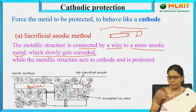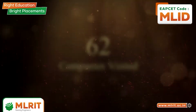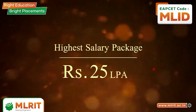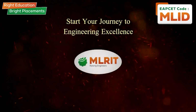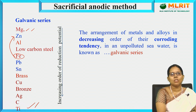Why have I chosen magnesium? Because when compared with an iron pipeline or stainless steel pipeline, magnesium is more anodic than iron. In this galvanic series we have magnesium, zinc, aluminum, low carbon steel, iron.